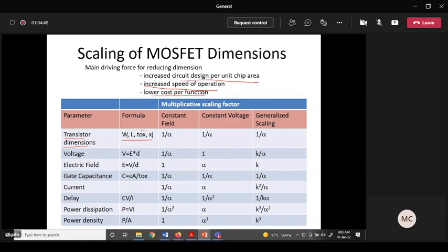They don't have any specific implication in reducing the device size, as you can see, because L is say here and W is this direction. So these two, if we can reduce, the overall device size or device footprint is going to reduce. But we will see TOX and XJ need to be reduced as well to keep the device performance intact. We can't keep TOX and XJ of the same value while reducing L and W, right?